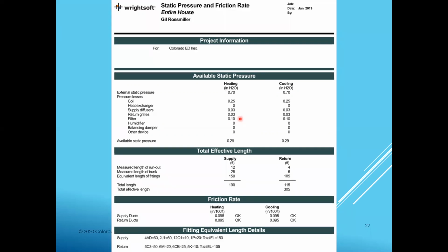The first thing they're going to do is run out and buy that Filtrete filter that isn't very thick, and they cram it into their furnace and wonder why the air conditioning and heat doesn't work as well. Well, it's because we didn't add any static for it, and it's got a static pressure that's as bad as the coil. So you've got to beware. It's just, like I say, a word to the wise, kind of a best practice piece.